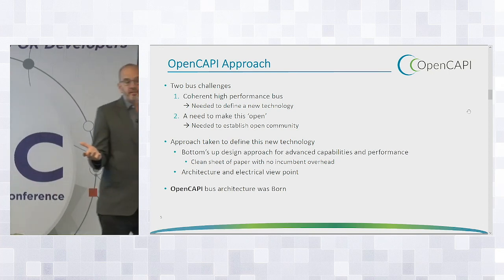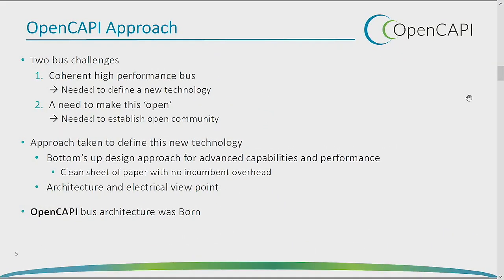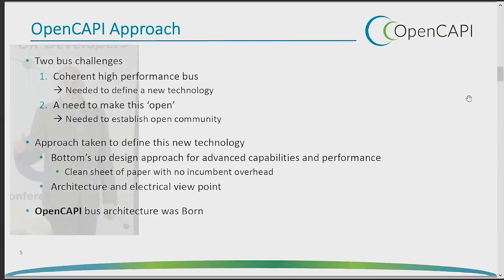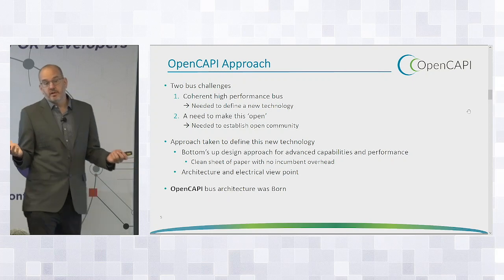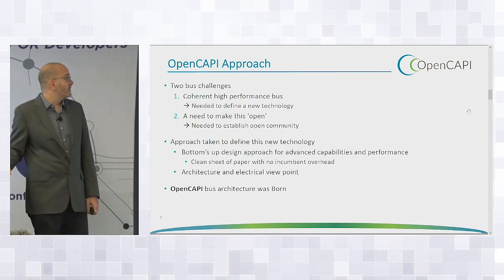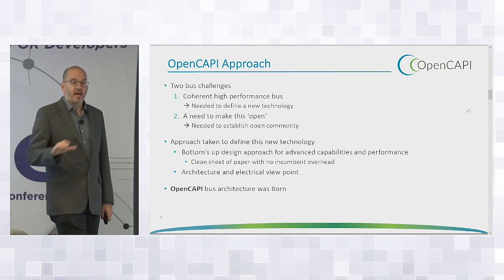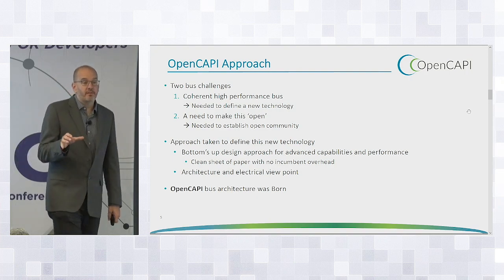We were looking at what we had before. So historically, we'd built accelerators using a PCIe ecosystem. And so we started back in Power 8 with doing coherent accelerators on PCIe. But the problem we ran into is the latency of a PCIe stack was much higher than we needed, right? I just said 700 nanoseconds to talk to PCIe, which is just tremendously too long. So we also needed to have a way to do coherence. PCIe doesn't have a typically good coherent mechanism in it.